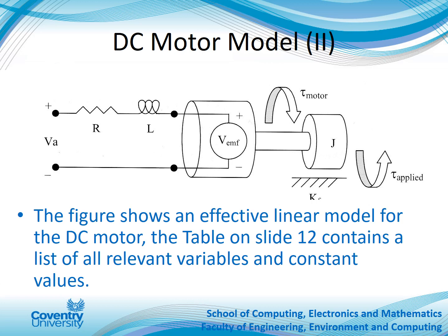So obviously I'd have a theta, which would be the angular position of this shaft. If I have a theta, I've got an omega, which is angular shaft velocity, in radians per second, and an alpha term, which would be the angular shaft acceleration in radians per second squared. Remember, if you differentiate position, you get velocity, and if you differentiate velocity again, you get acceleration.